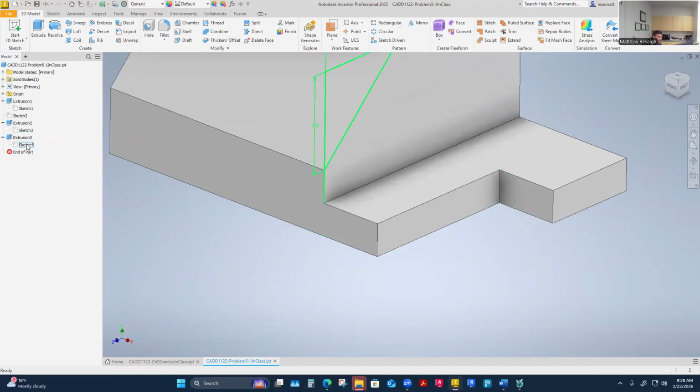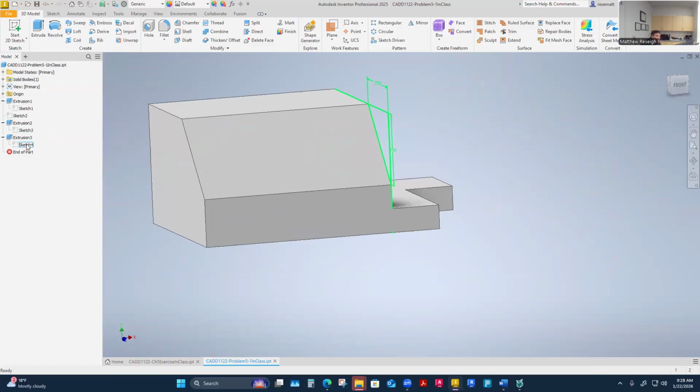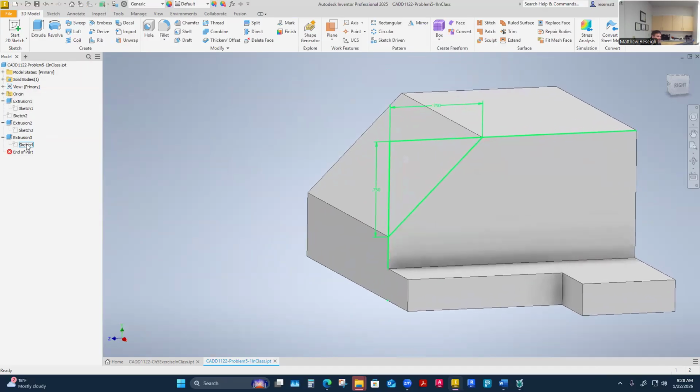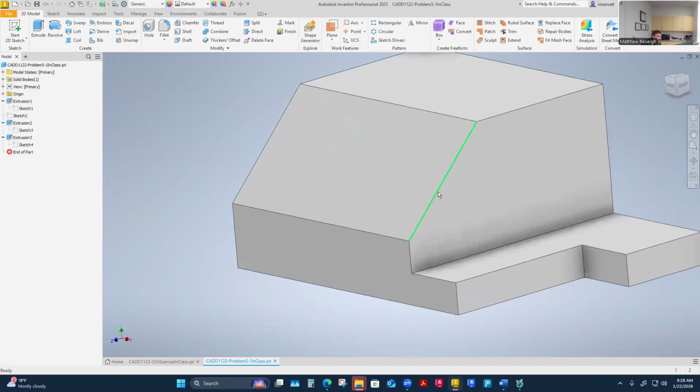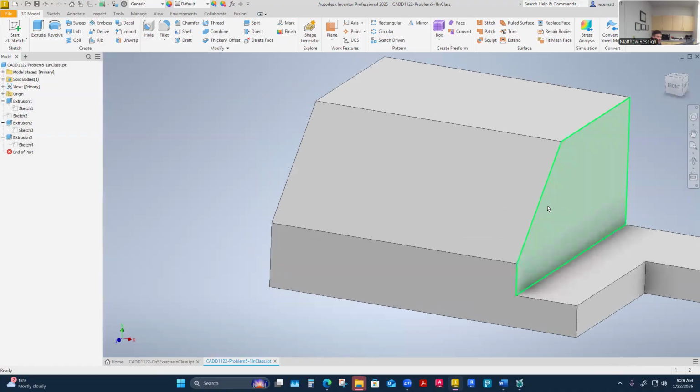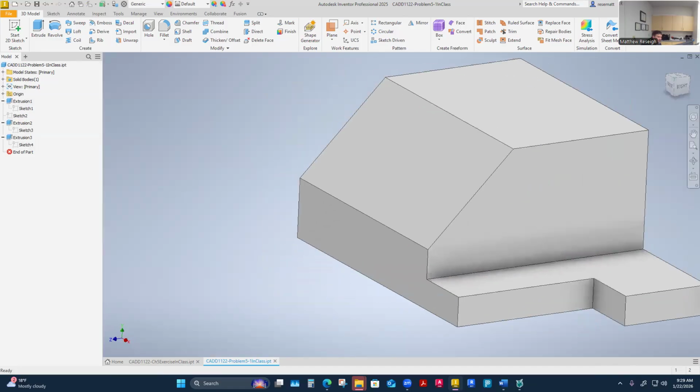And then the next thing for me is this sketch here on that face, which mine, I can tell my extrusion is through all too. That's why mine's cut through. And that's why on Lydia, yours stops right here, because the way this one is extruding and cutting through, yours is because it's a dimension. So it's not cutting all the way through, which is okay. Let's look at the sketch though first.